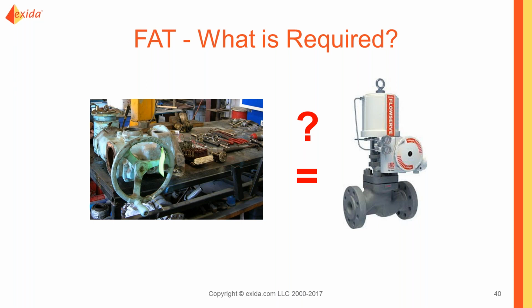So depending on the complexity of what your final element actually is, doing an actual factory acceptance testing before equipment ships can be very beneficial, and if done properly, it's going to generate documentation confirming that the integrated assembly or the pumping system or the MCC is correct and suitable for service. So you don't have to do it, but it can be a pretty useful technique for unique solutions or special systems.